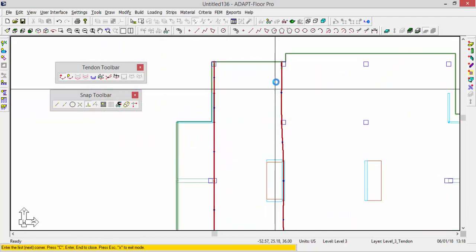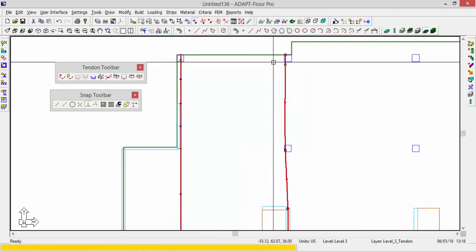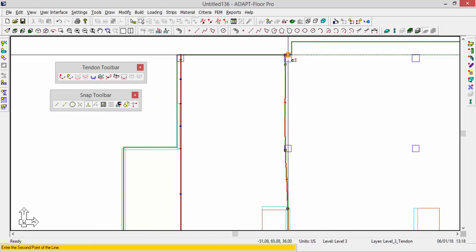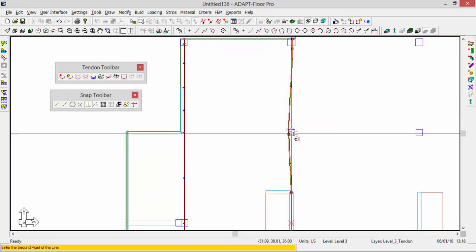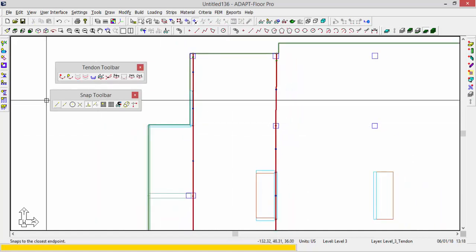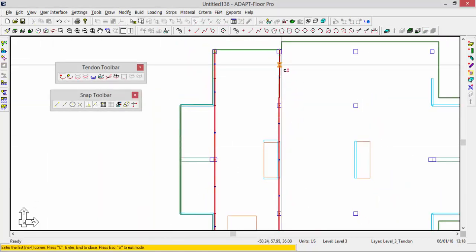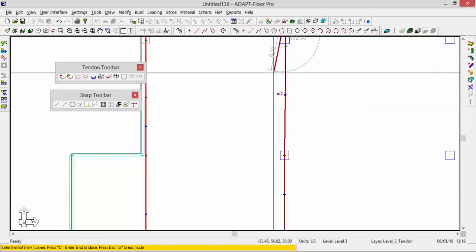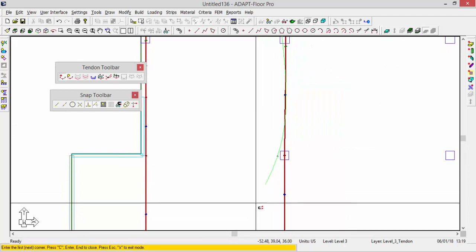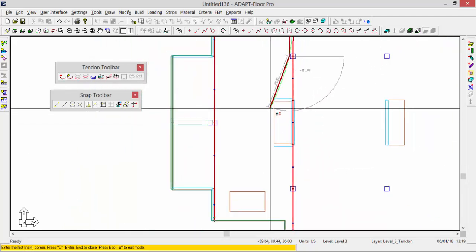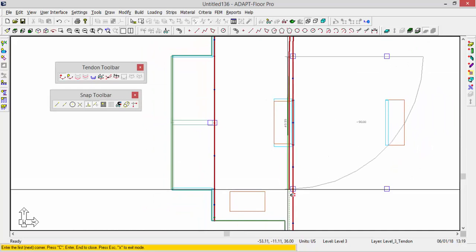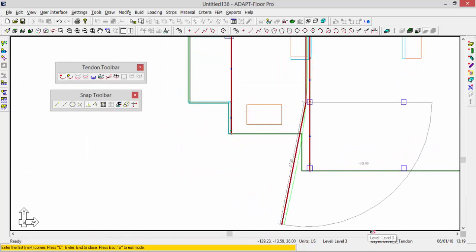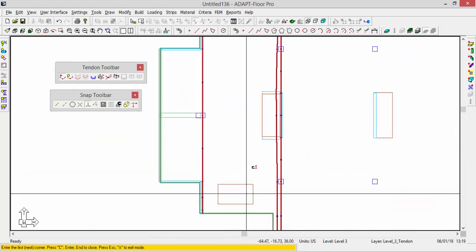Now we could also do tendon swerving. We might readjust the position of this cable, for example, and I'll go ahead and do that like so, and I might readjust this, move it over closer towards the center of the column. And in this case, we might have a split cable that wraps around this opening, so I can model that particular instance by just modeling this straight through, and then I'm going to add swerve points that allow me to provide the in-plane curvature for the cable.